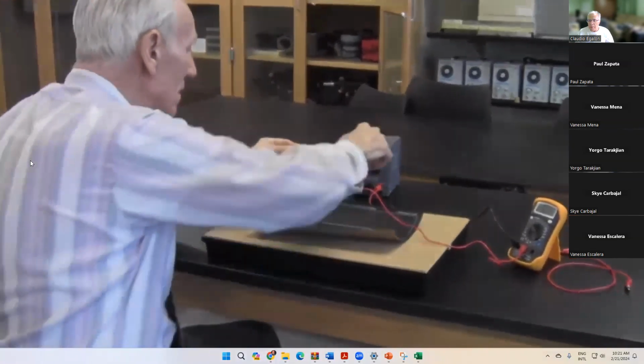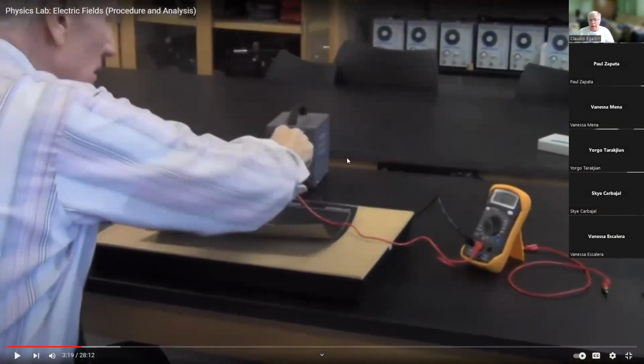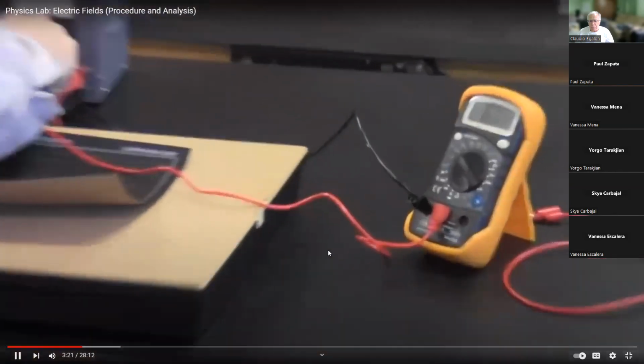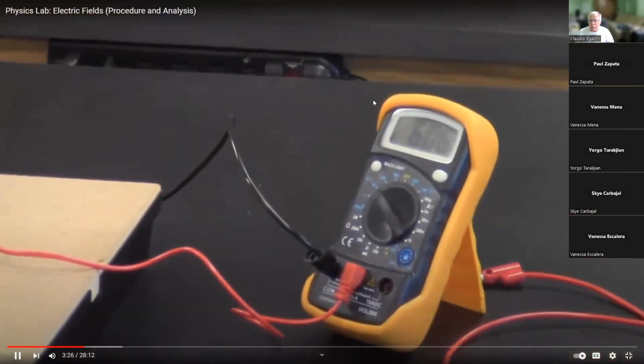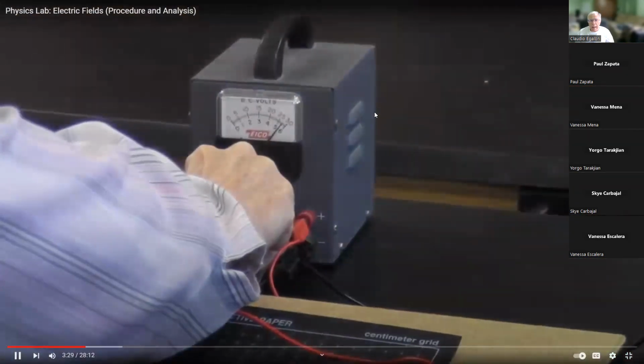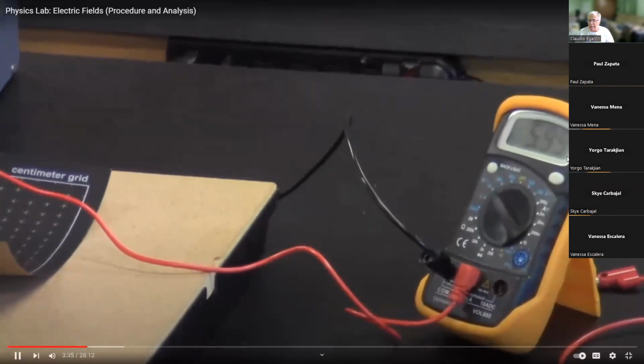So let's check that out. Okay, it's a little bit high. This is very delicate. So what he's doing here is measuring the output of this power supply. That's why he says 6 volts. So I can turn this down just a little bit more, so it stays at 6. Closer to 6. Yeah, okay. He wants to set it to 6 volts, though we usually set it to 10 volts on this power supply. Oh, that's close enough. Yeah, 5.99. That's 6 volts.